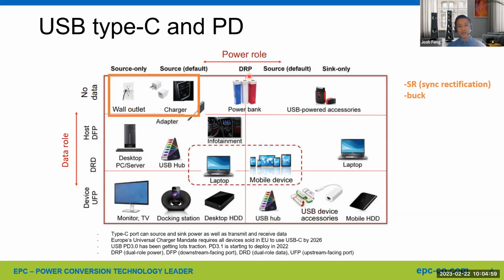And there are a couple of different sockets out there. For example, a charger device: on the secondary side, you have SRs or a multi-port buck converter. On the primary side, you can have a PFC plus ACF topology, or totem pole plus some of the newer asymmetrical half-bridge topologies, which are typically more addressed by high voltage GaN devices these days. On the DRP side, dual role power, we're seeing some of the sockets, for example buck converter and buck-boost converter, getting more popular.